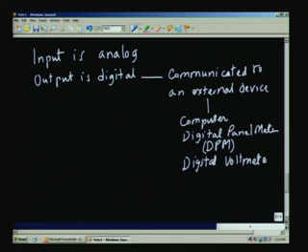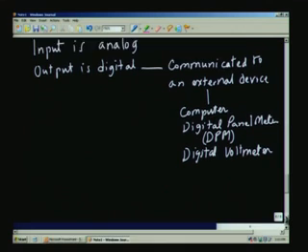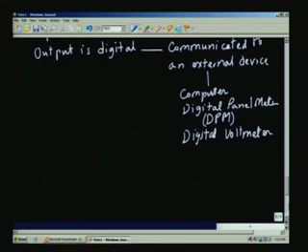Of course, in the case of the current loop, we can also measure the current directly using an ammeter. That is one option which is always available. So, this simply means that if the output is to be digital, I have to convert it from analog form to digital form, and that can be done by using a suitable analog to digital converter.